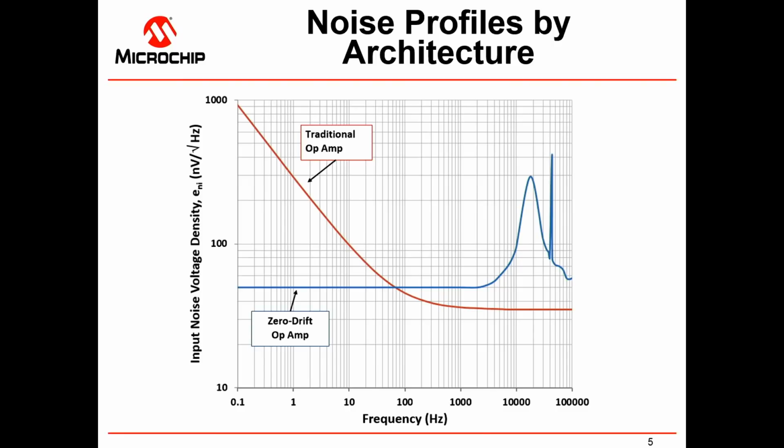and that causes the noise to rise up. And it's sort of inherent in pretty much all of the zero drift architectures. And the spike I wanted to mention is simply the feed-through of the clock tone. Oh, okay. Because of the internal switching that's going on. Yes, the internal oscillator and the switching action that occurs, yes.